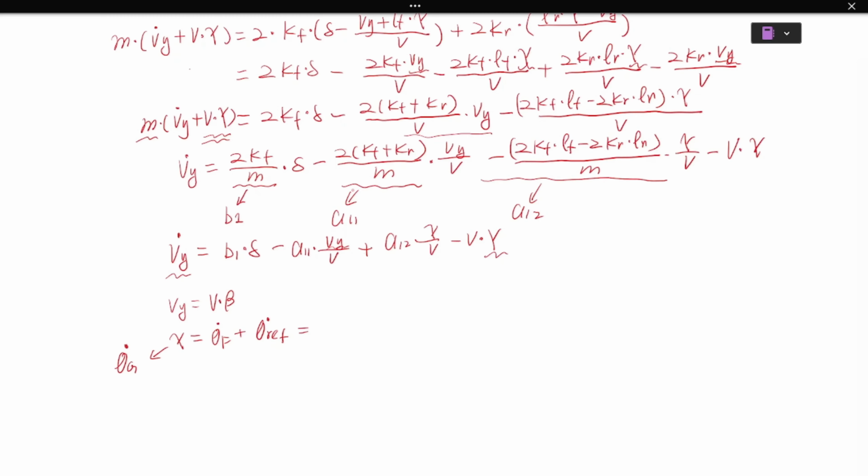And this equation goes to theta f dot plus v times the curvature of the trajectory rho ref times cosine of theta f plus beta over 1 plus rho ref, the curvature, times fpy. You can check this equation in the last episode.